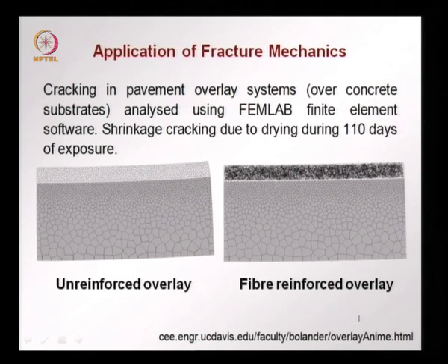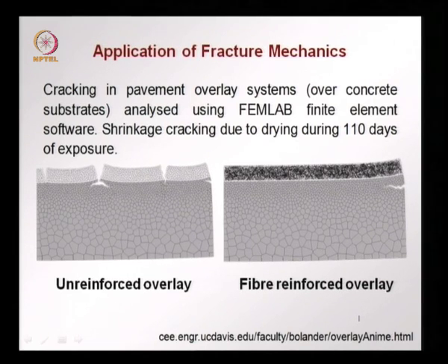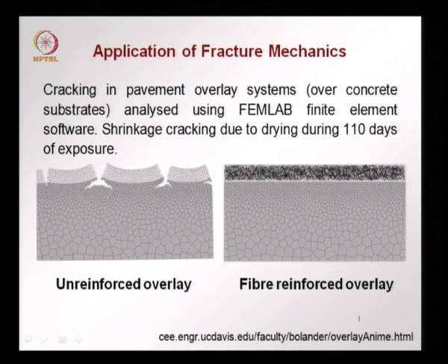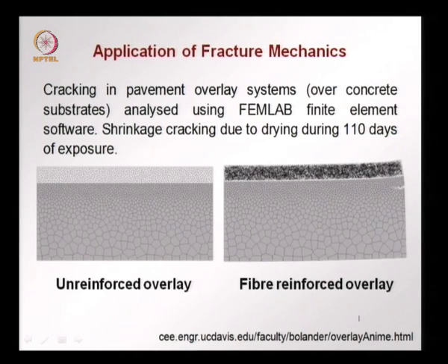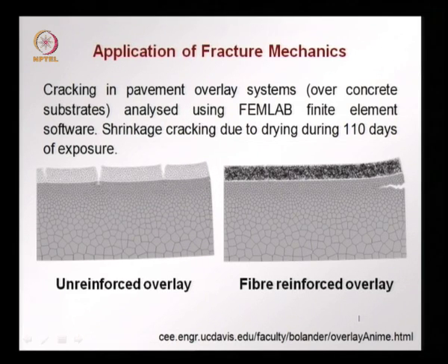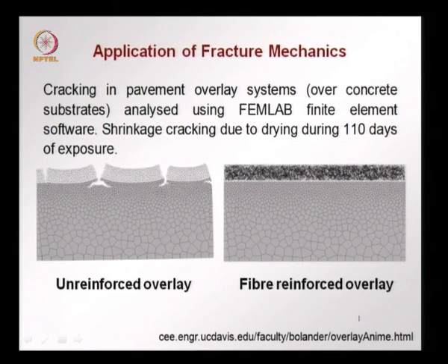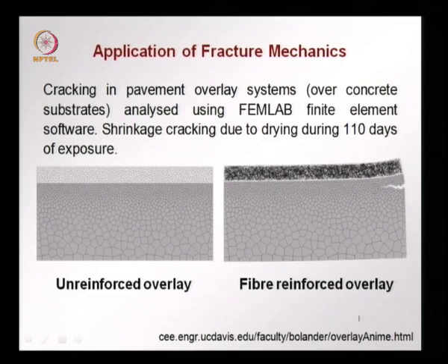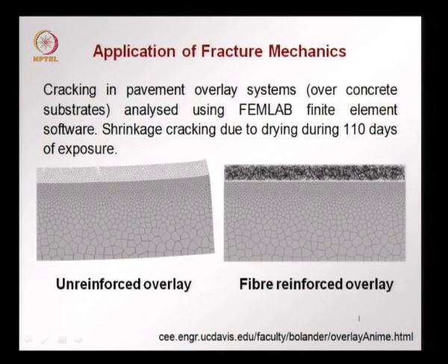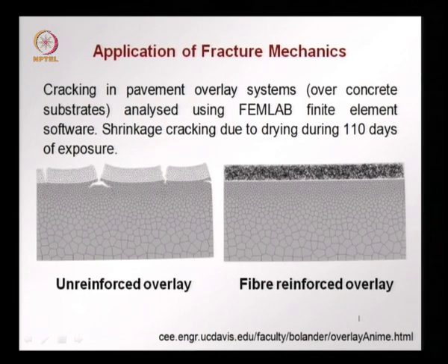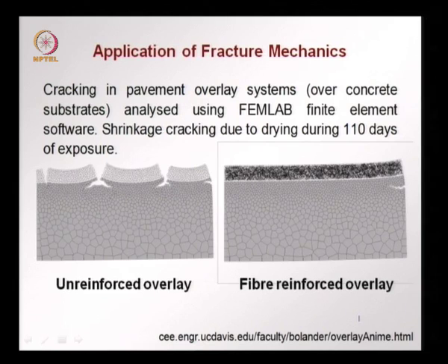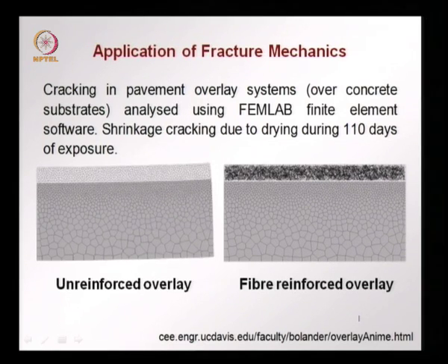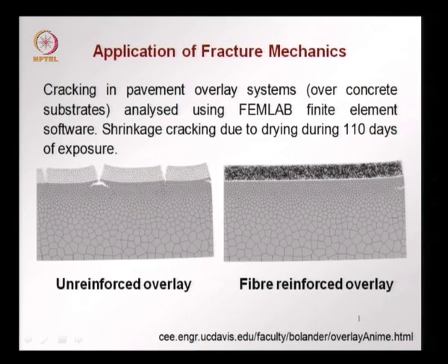Another simulation is from the group of Professor Bolander from the University of California, Davis, where we see a simulation of concrete overlays subjected to shrinkage. On the left we have an overlay that is plain concrete, on the right we have an overlay that is fiber reinforced concrete, and this is what is expected to happen due to shrinkage over a period of 100 plus days, and this was simulated using their software called FEMLab.